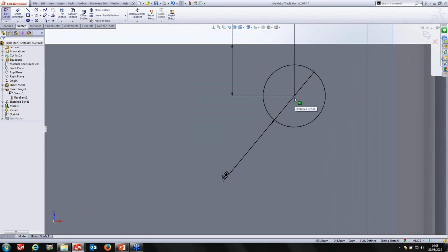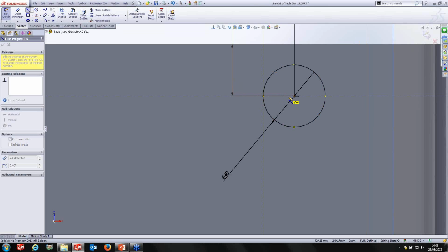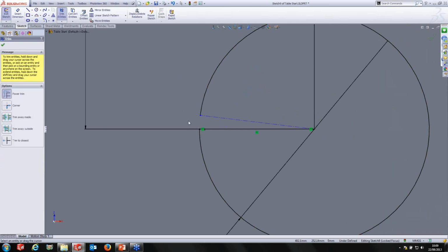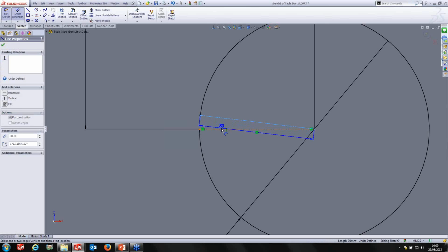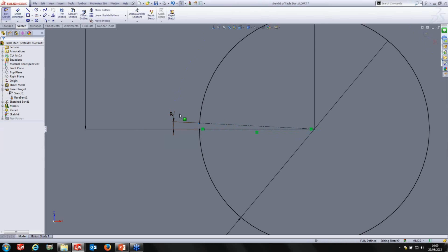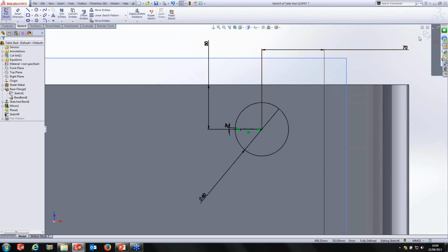And then also, because it's a sheet metal design, need to leave a region for the model to unfold from. So I need to put in a slight gap on this sketch. In order to do that, I'm going to use my construction lines. And if I just draw a construction line across the model and then back out to the edge again, it just gives me somewhere to actually trim away. So if I just trim away this little region in here using the trim tool, I can then just dimension the angle between these two lines just to make sure that it's fairly consistent. So I'll put that at 3 degrees. That gives me a small gap just to unfold the model from.